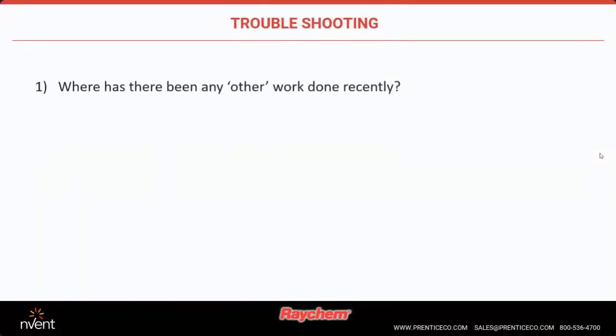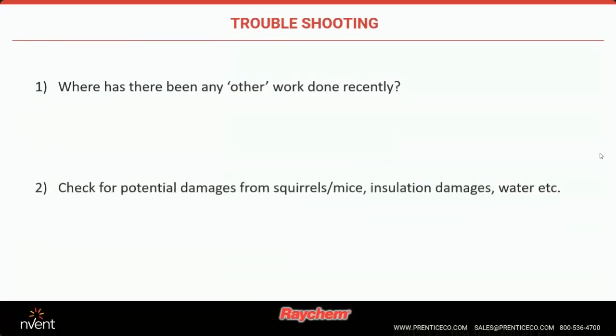All right, let's get into some troubleshooting. Troubleshooting, I find oftentimes if you have a system that is working fine, it's been working, no problems with it, and then all of a sudden one day out of the blue, it's either blowing a breaker or it's tripping because of ground fault, I highly suggest looking at this job site as a whole, looking at what other work is being done in the area. In a lot of cases, that's going to get you directly to potentially where that problem is.